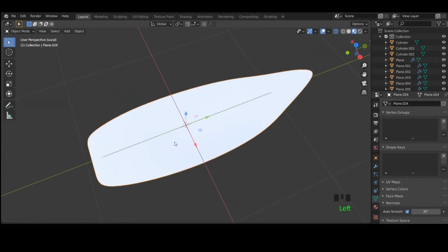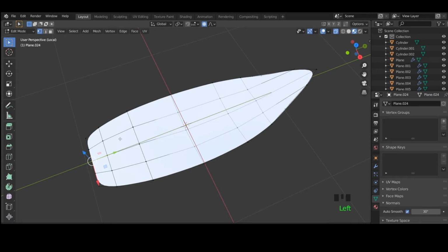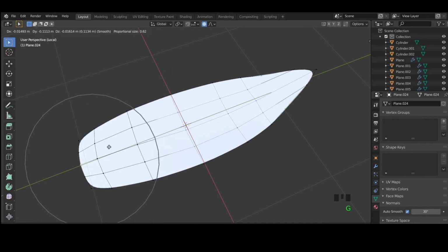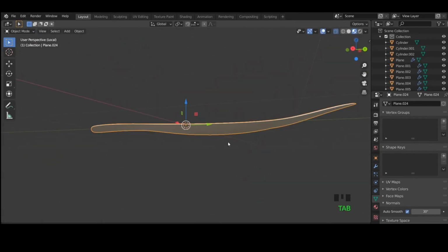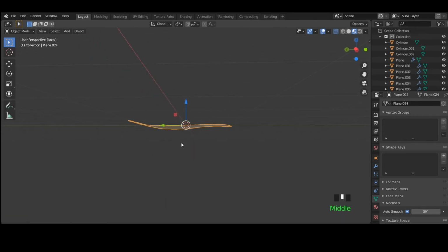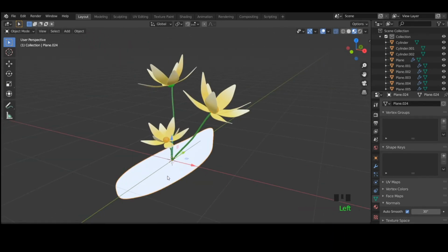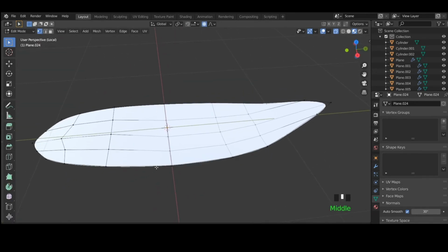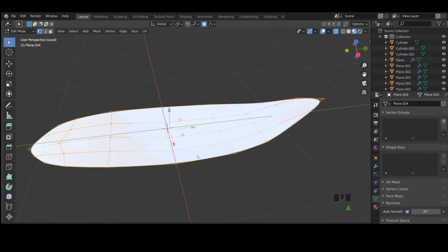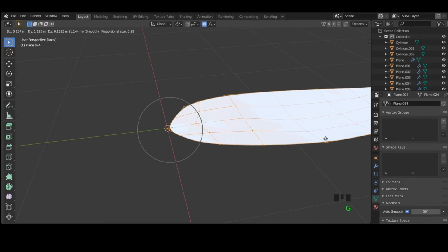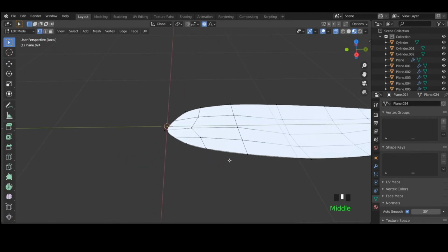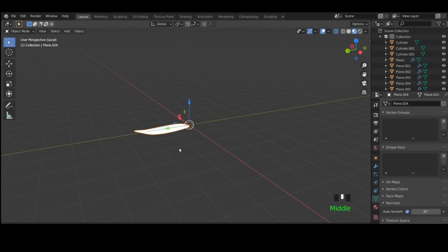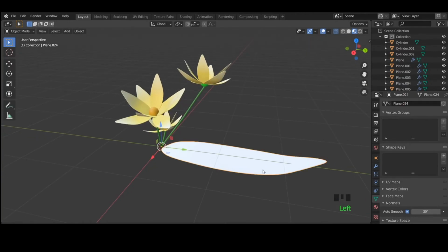Okay, let's go back to edit mode, select this vertex, grab slightly. Okay, tab out. Now slash to get back to all editing. Oh, one thing, we need to get back to this and then select everything. I just want to adjust the pivot point to be here. Okay, all right, tab out, slash to get into all mode, and then now scale it down.